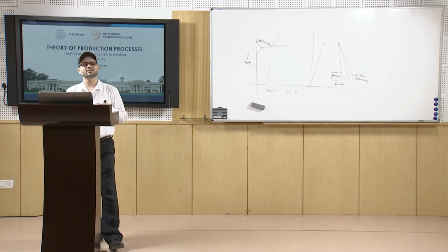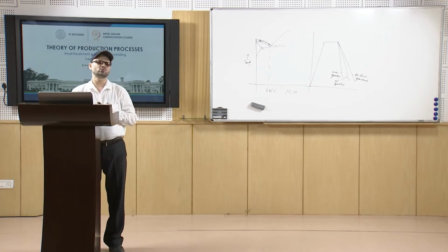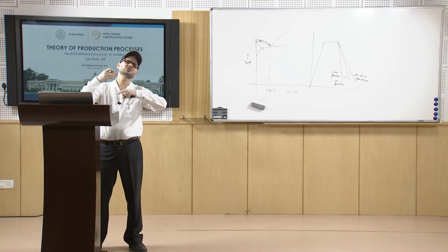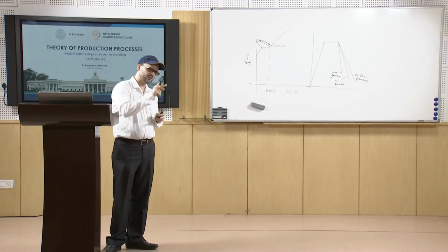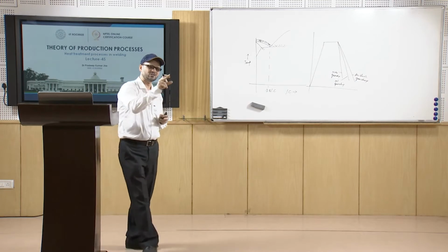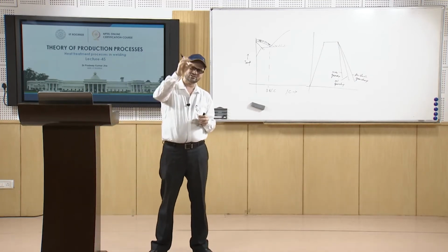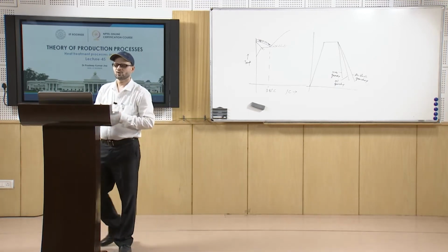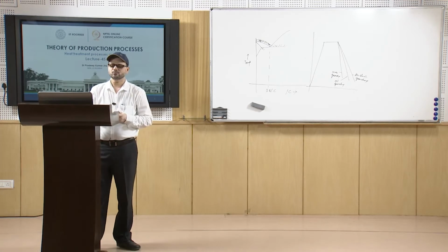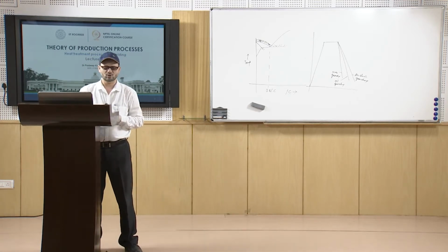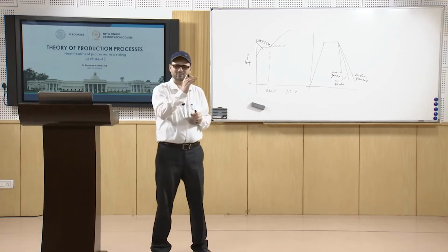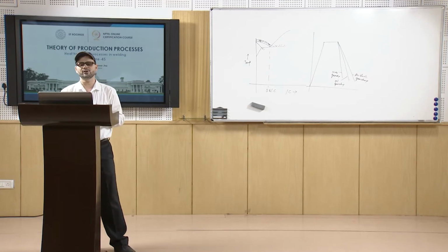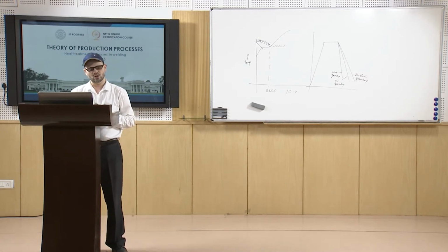and the tempering treatment is done by heating it to a lower temperature zone. That temperature zone may be from 200 to about 650 degrees centigrade. So, you are heating it in that temperature zone, either towards the higher side or the lower side, then holding it for quite a long time depending upon the properties required, and then allowing it to cool in the air. That is the normal tempering treatment which we do.